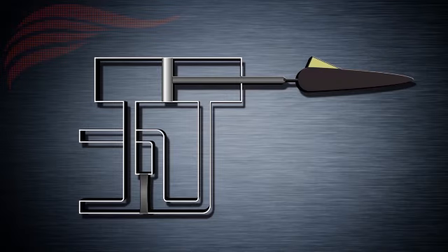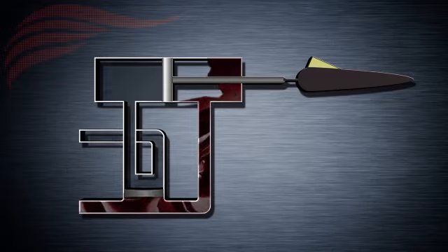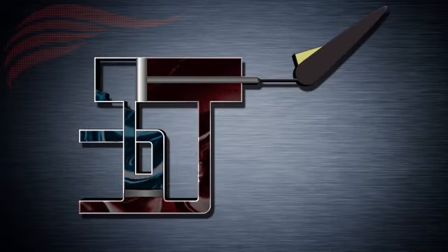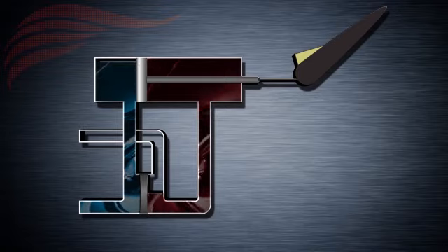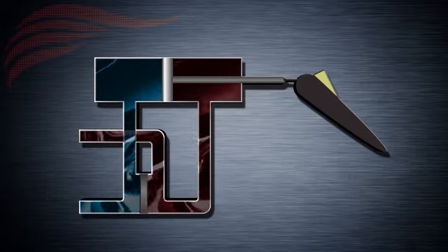This diagram depicts an aircraft elevator actuated by a single piston. A selector valve rotates through 90 degrees to route hydraulic fluid either side of the piston head to move it back and forth. To pitch the aircraft up, the pilot pulls back on the control column and the elevator will move up accordingly. When the control column is moved back, the hydraulic fluid is pumped under pressure into the actuating cylinder, forcing the piston backwards and lifting the elevator.